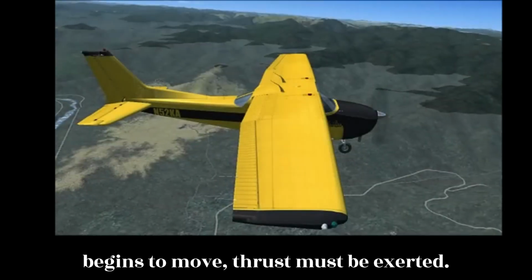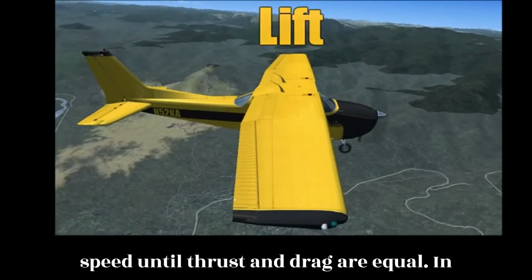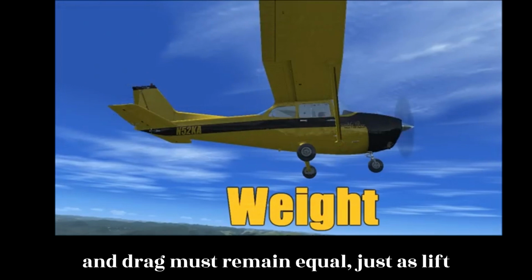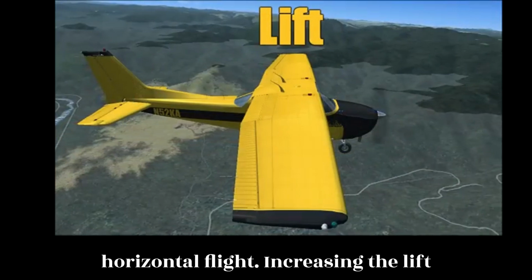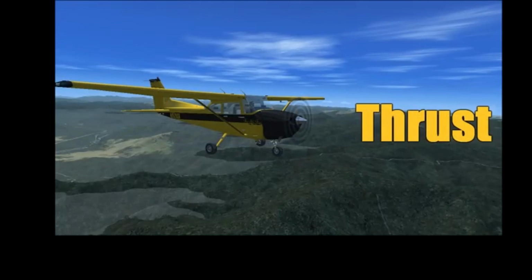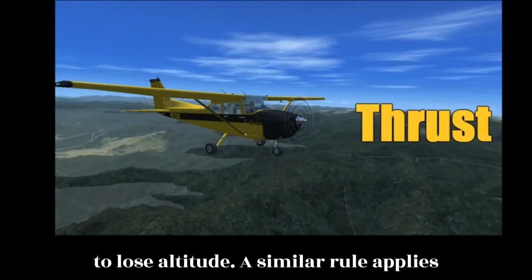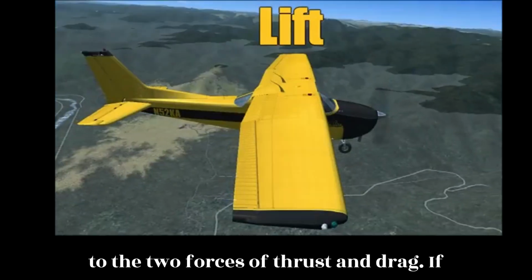Before the aircraft begins to move, thrust must be exerted. The aircraft continues to move and gain speed until thrust and drag are equal. In order to maintain a steady speed, thrust and drag must remain equal, just as lift and weight must be equal for steady, horizontal flight. Increasing the lift means that the aircraft moves upward, whereas decreasing the lift so that it is less than the weight causes the aircraft to lose altitude. A similar rule applies to the two forces of thrust and drag.